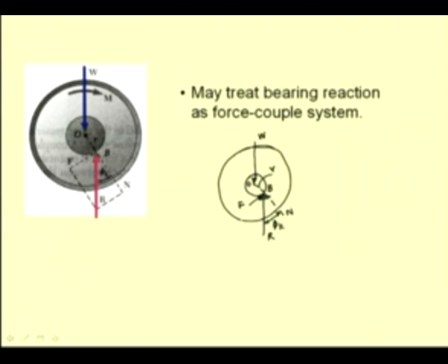Now, I can replace this resultant force R by a force that passes through point A, which is the lowest point of contact, just below O, the center of the axle, and replace this by a force R and the moment due to this force acting at point B. So, this can be replaced by this force R and the moment.